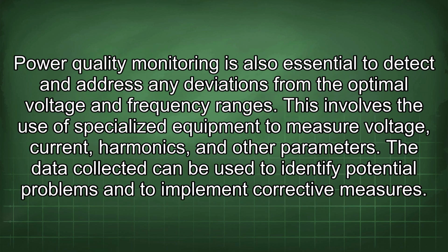Power quality monitoring is also essential to detect and address any deviations from the optimal voltage and frequency ranges. This involves the use of specialized equipment to measure voltage, current, harmonics, and other parameters. The data collected can be used to identify potential problems and to implement corrective measures.